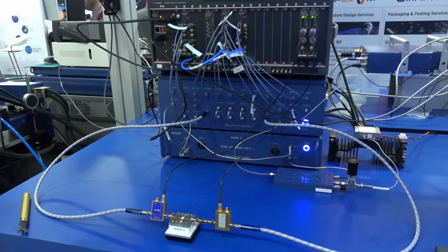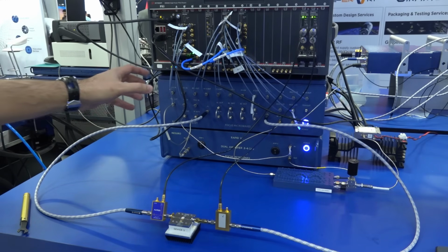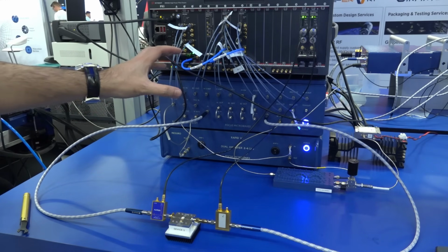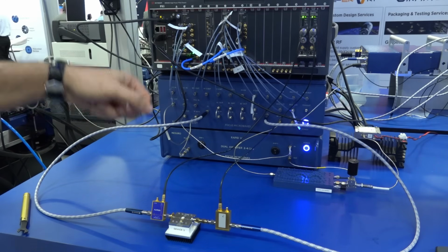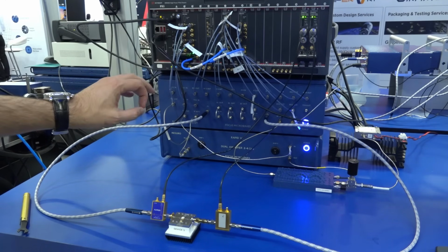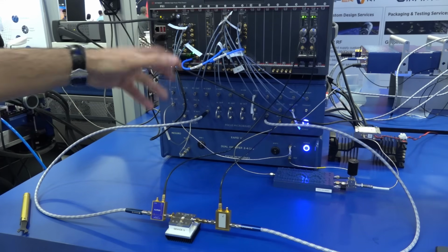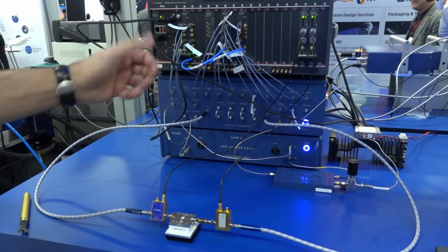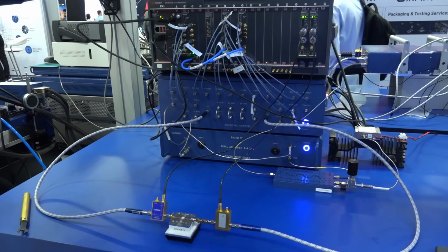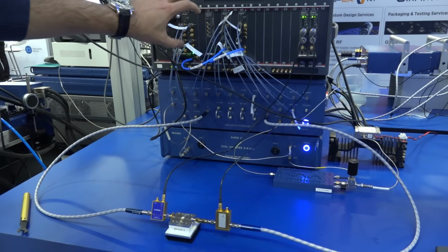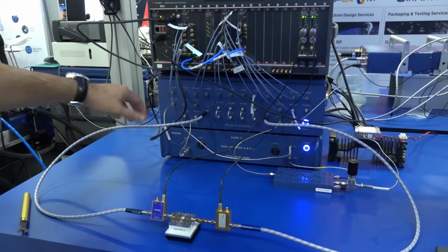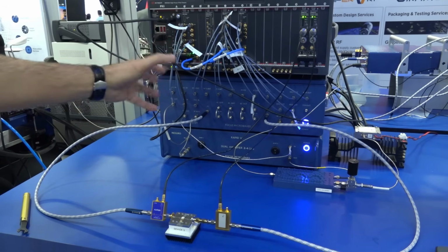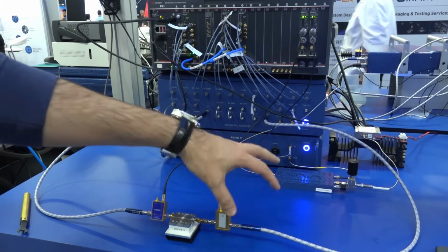So here at Focus Microwave, we have the rapid load pull system. So these systems are quite complicated because you are exciting the input and the output of the DUT with your custom waveforms, in this case fully modulated, in order to emulate different points on the Smith chart. You're doing an active load pull system. So this is based on a PXI from Keysight, so you have a complete direct digital synthesis DAC generating the waveform you want. It can be any waveform. And that goes into their box, which does all the conditioning in order to apply the signal to the input and the output of the DUT.